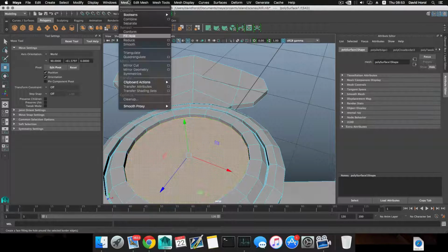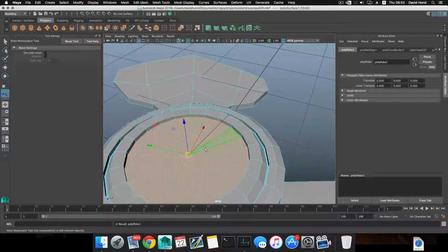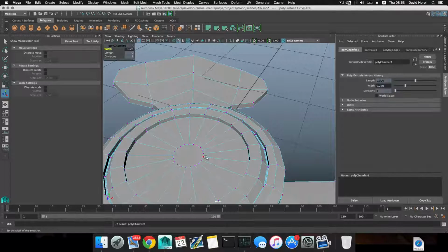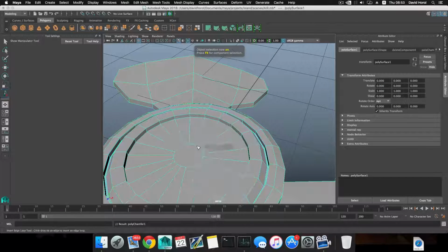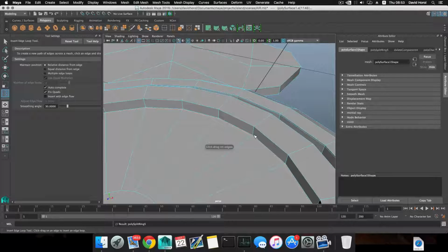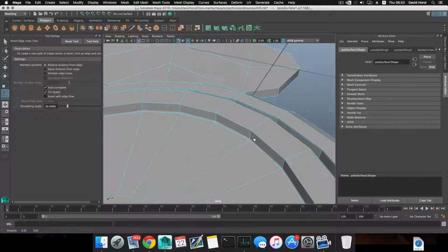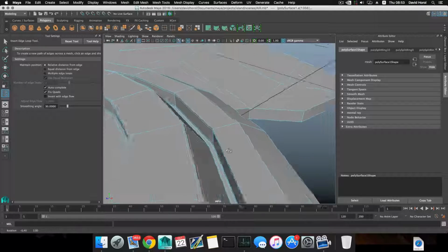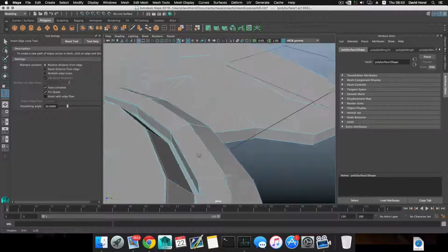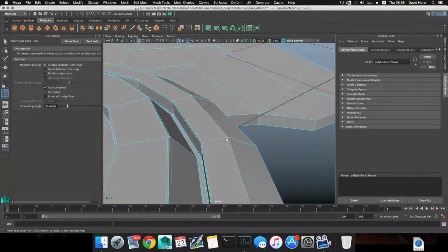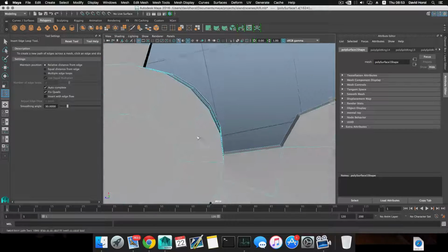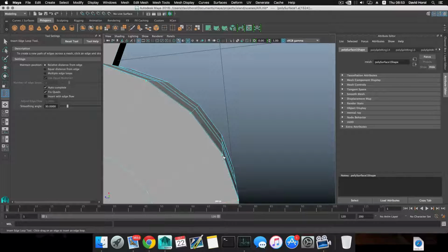Let's first take this one, poke this, right click, choose vertices, click on the background, and then grab this middle vertices, shift right click, chamfer it, press F8, shift right click, and let's insert some edge loops. One here to support this corner one, and one from here to support the same corner one. This corner, we need one from here, and one from here. One from here, and one from here. And because we already created all the necessary edge loops there on the fly, we just need one here, one here, one here, one there, and I'm gonna add one here to maintain this area.